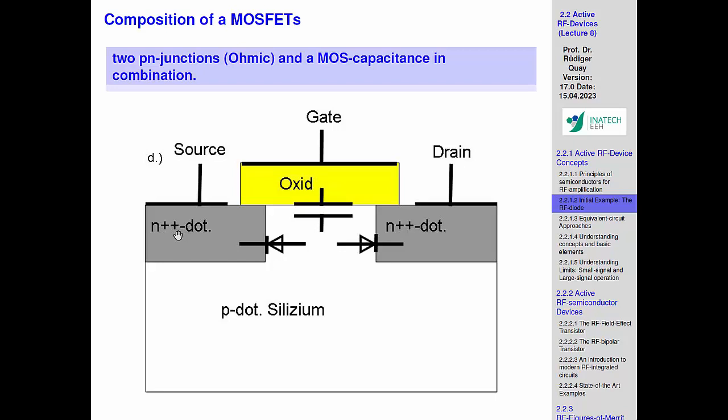Yeah? So it's about the resistance of this region, but it's also definitely of the contact region, which then is suppressing any inhibiting effects. Yeah? So here we are good, and here we are particularly isolating. So we are not sending any carriers into the substrate, which would be bad, because if we're trying to control here and something would be flowing below in the p-type silicon, we would have a significant problem. Yeah?